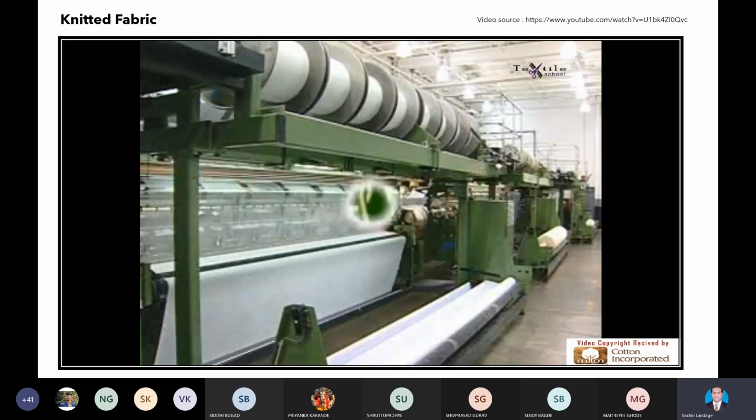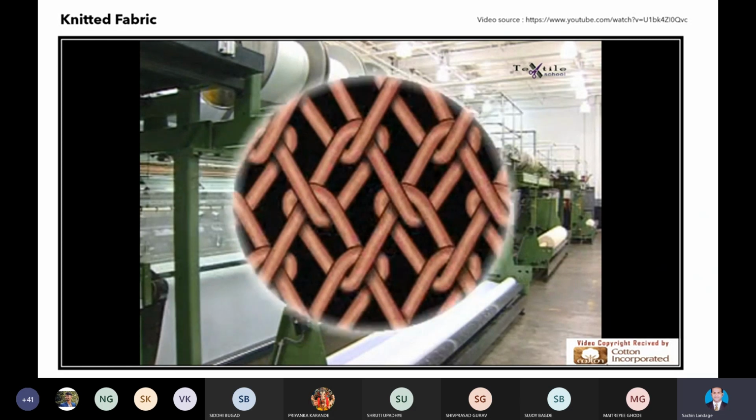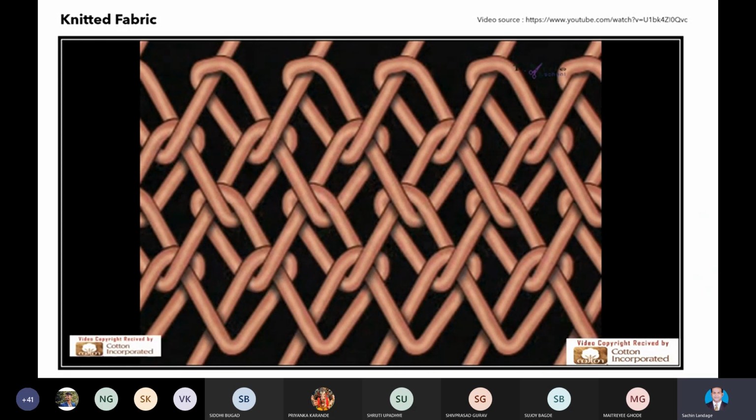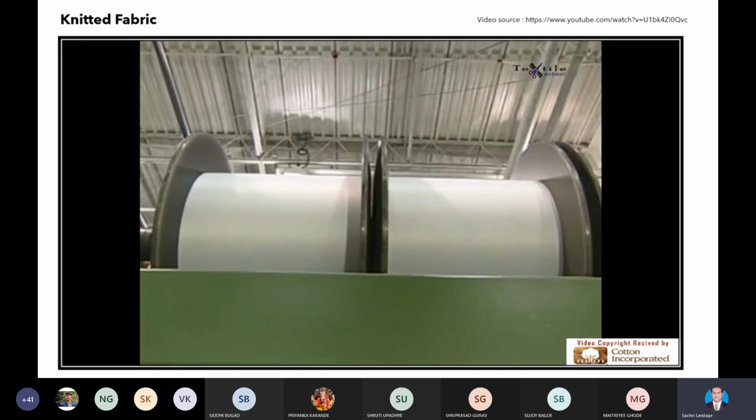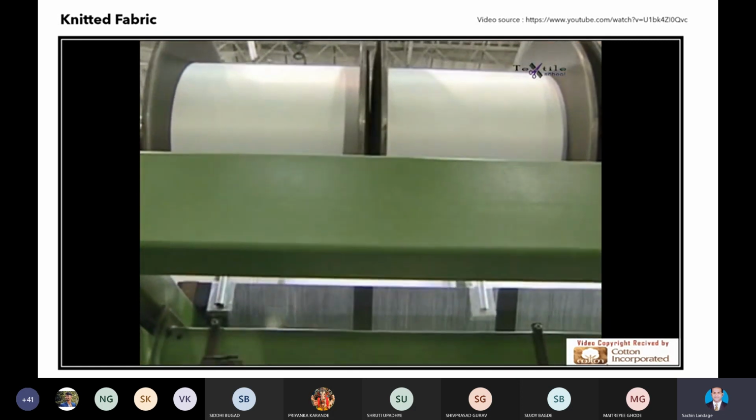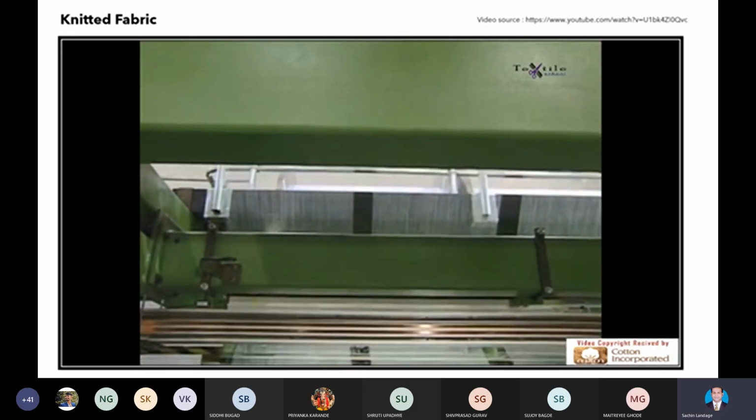The second system used for knitting is produced by machines that are designed differently, to knit vertically. This illustration shows you how warp knitting, in contrast to weft knitting, is accomplished by forming loops in a vertical direction. If you look closely at an illustration of warp knit, you see that the yarn is intermeshed vertically with 2 wales. With warp knitting machines, each individual loop is created from separate lengthwise yarns.